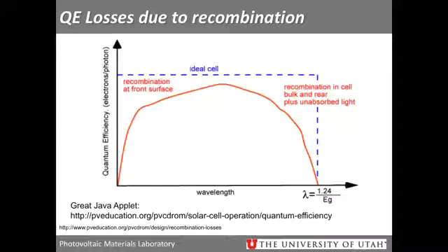In inorganics, in thin film solar cells, where we have, and I'll show you the band diagram, larger band gap semiconductors stacked on top of your light absorbing layer, you can lose QE from absorption of those higher band gap layers. So for example, cadmium sulfide is a common N-type junction partner for a lot of thin film solar cells, and that will absorb at a certain wavelength, and so you'll see a step in your EQE when that starts to absorb.